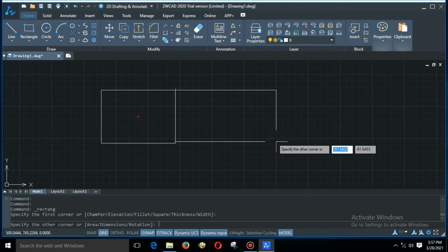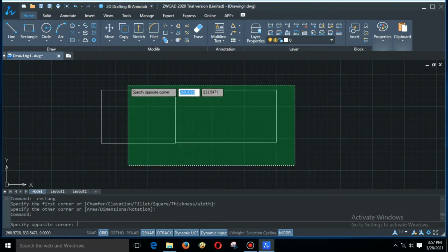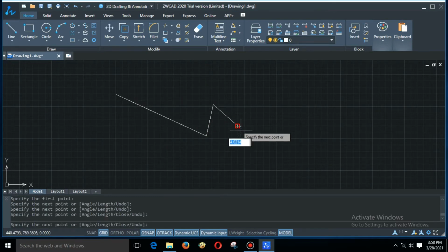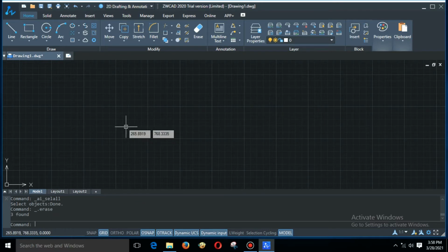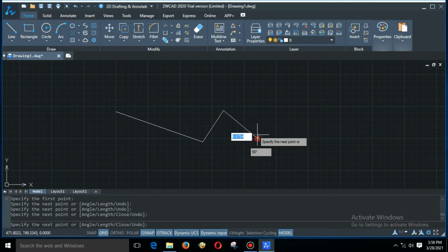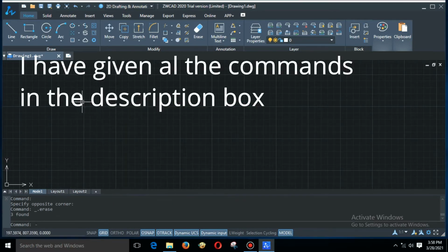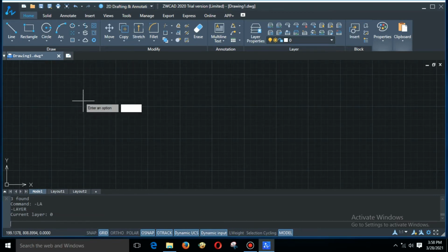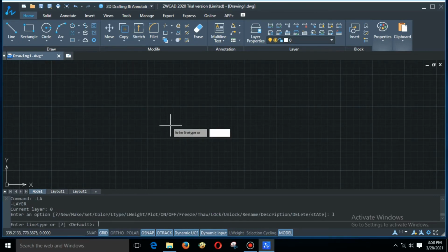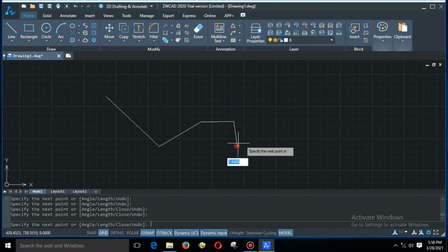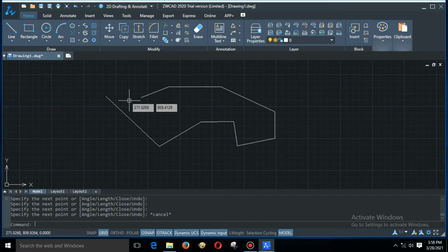Now one way of doing all of this is with commands. Let's talk about that first. Like I said, for a line you have to draw this and that and that. But what you can also do is use L and press enter. That's it. You can use L enter. That's the command for it. So no need to press every single button. Use L and enter. Sorry, I pressed the wrong button by mistake. That is L enter.